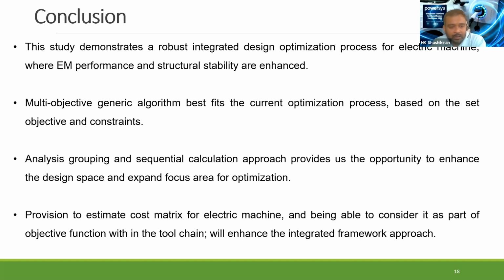Typically the magnet temperatures and the overall machine saturation are the few areas that change with each machine design, and they are usually estimated. If you look at the test, they don't exactly measure the magnet temperature, or exactly measure the saturation. They are estimated based on the manufacturing processes or other priorities.